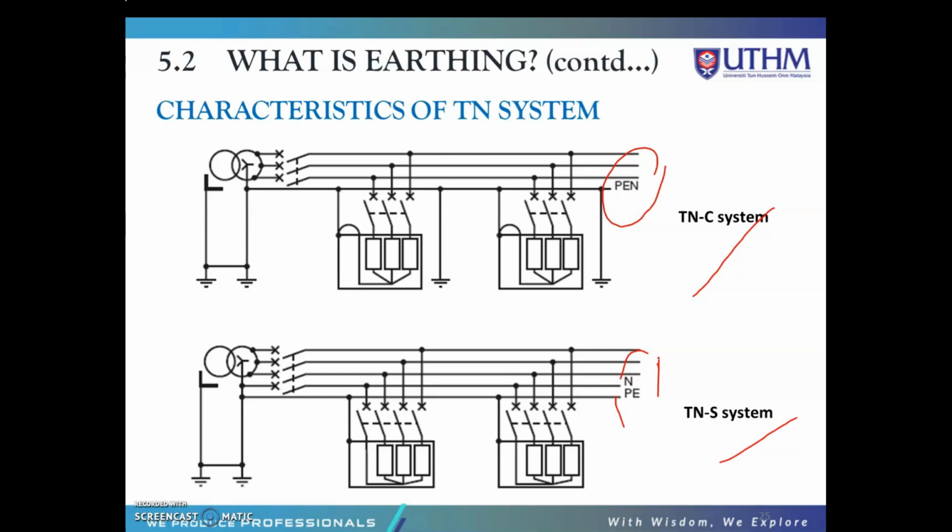It requires that any modification or extension be designed and carried out by a qualified electrician. It may, in the case of insulation faults, result in greater damage to the windings of rotating machines, and on premises with a risk of fire it may represent a greater danger due to the higher fault currents.